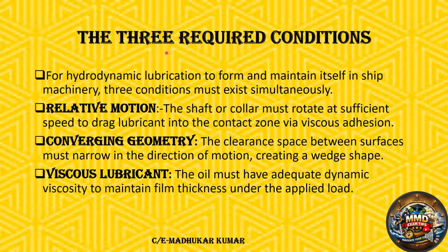So the three required conditions for hydrodynamic lubrication: one is relative motion, another is converging geometry, and the third is a viscous lubricant. Yes, lubricant quality is also very important. If it is not sufficiently viscous, or the property of the lubricant is not such that it can carry the load, if it is not thick type, if it is a thin type, then the separation cannot exist and the contact will happen.